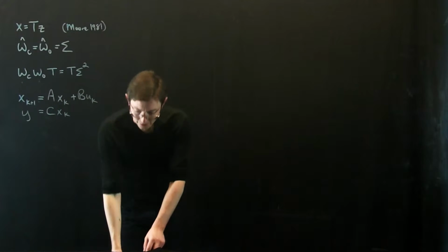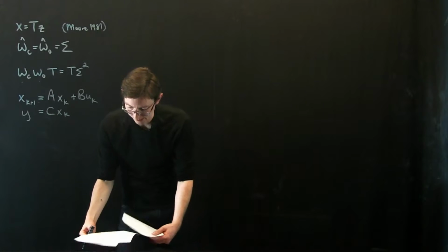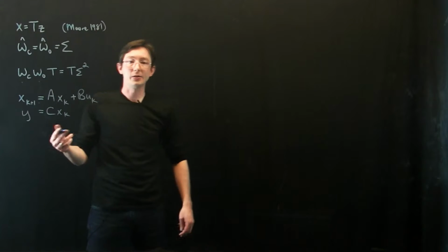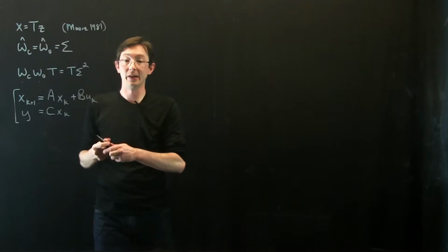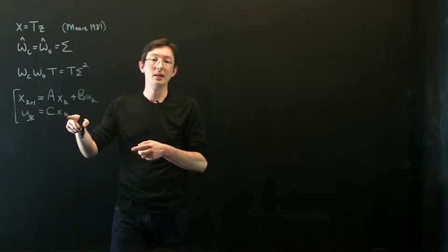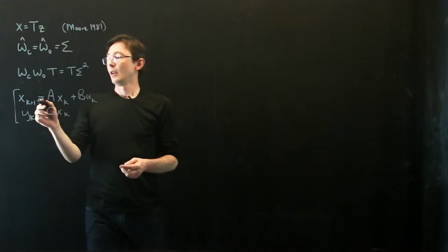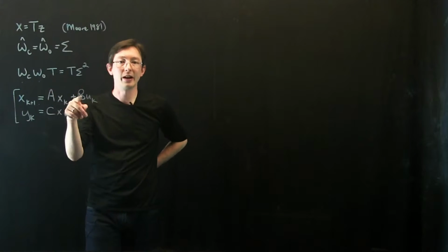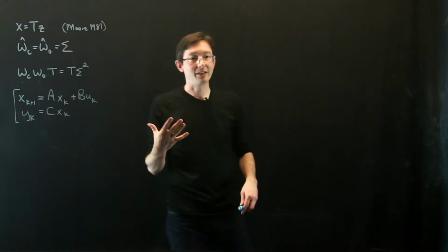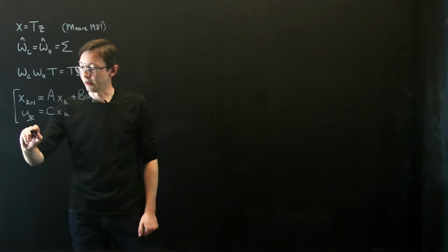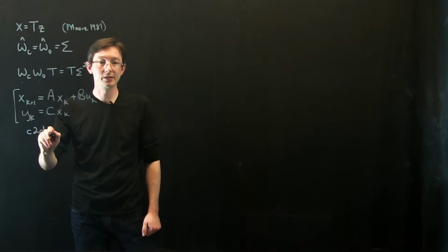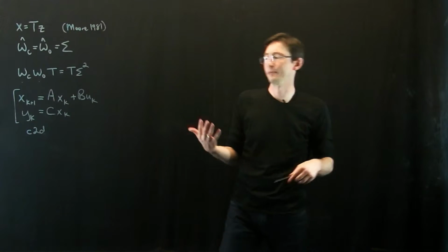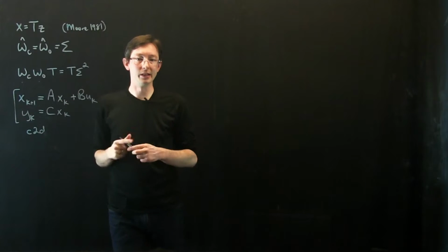And I think something else important here is looking at the adjoint system. So the adjoint system here, this is basically my dynamics written in discrete time, so time step k delta t. And these A, B, and C matrices are different than my original A, B, and C matrices, but there's formulas for how to get these. And if you want to do this in MATLAB, there's a super simple command called C2D, continuous to discrete. Or you can go check the Control Bootcamp for how to go from a continuous time system to a discrete time system. Anyway, this will make it a little bit easier.